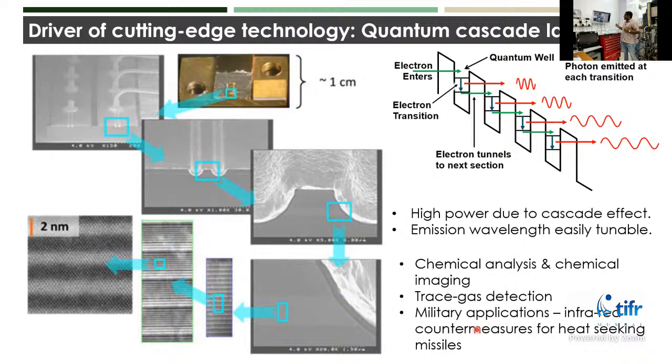Okay. Now, if you look at one such laser, and you zoom in and in and in, at the heart of it is this kind of layered material. And this ability to create this layered material is what makes this kind of technology possible. So just very quickly, you have created a semiconductor with a smaller gap, and you have sandwiched it with a material of a larger gap, giving rise to something called a quantum well.